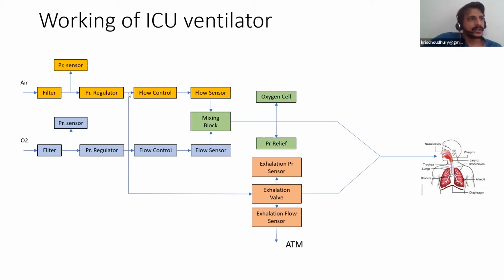Based on that, you can see a small amount of air is taken from the input airline, and this is controlled with the right valves to ensure that whatever PEEP is set by the doctor is executed on the patient. You would have a diaphragm: on one side you have the patient pressure, and on the other side the pressure set by the doctor.